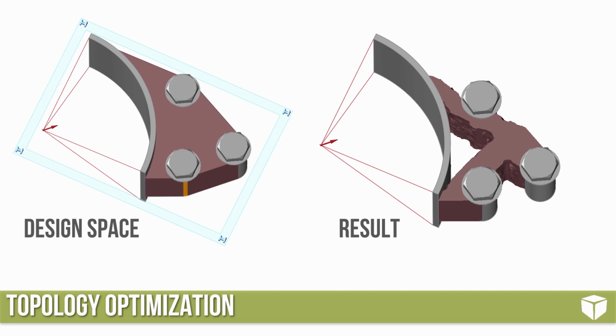But in my goal, I may have overestimated or underestimated how much material I can remove. Potentially by removing 70% of material, I end up in a situation where my factor of safety is less than 1. Or my factor of safety might still be 5.0. So I could actually remove more material.